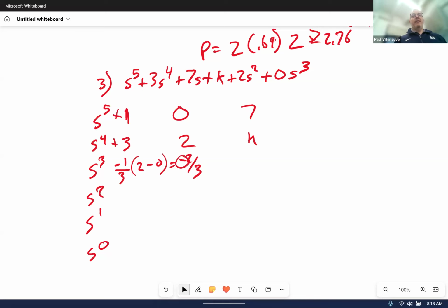Plus, minus. And since that value of K is not in there, you're done. There's no value of K that results in a stable system. You don't have to do any more work. You stop right here, because I can do anything I want to K, and it can never make -2/3 positive.